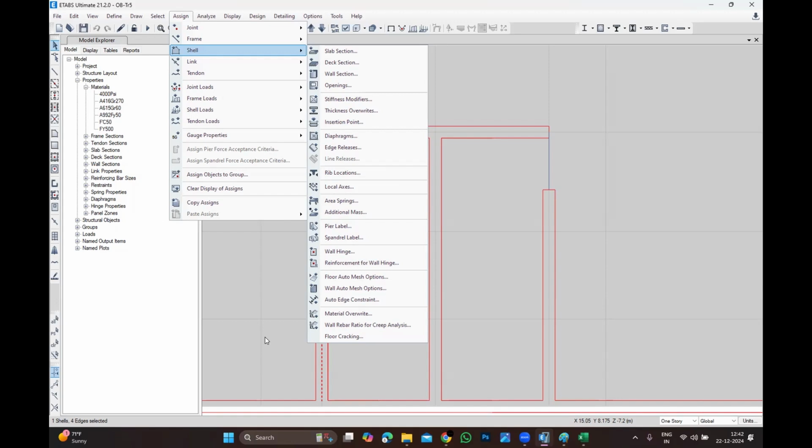That is the reason that in a precast structure, when you want to have any kind of opening after it has been executed and casted, people will never go for it without checking. People will just check the drawing, whether they designed it as a beam or as a wall. If it is a wall, it's fine, you can open it. But if it is a beam, then you're directly cutting the bottom rebar. So many precast buildings have collapsed in the DIP area.